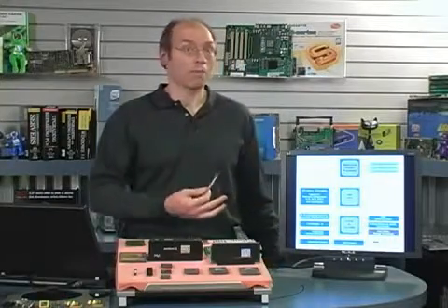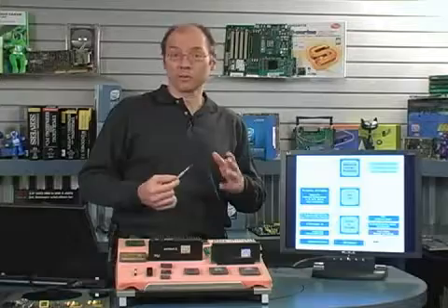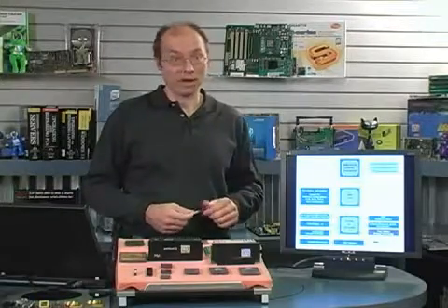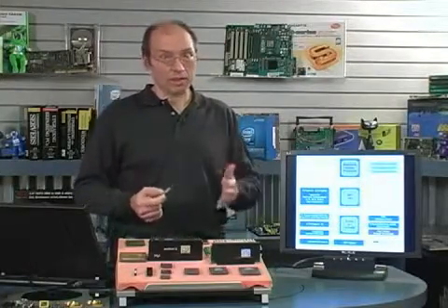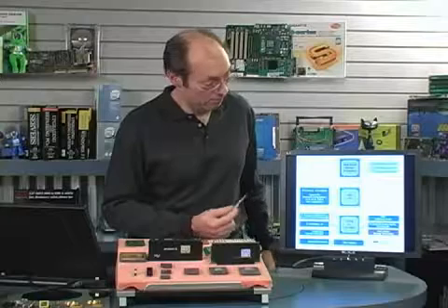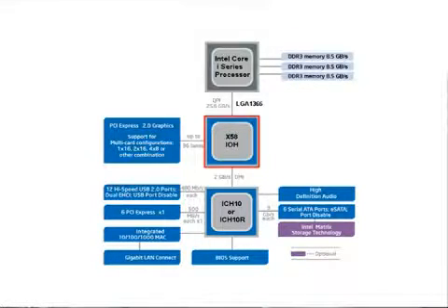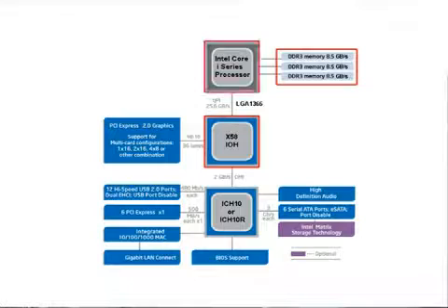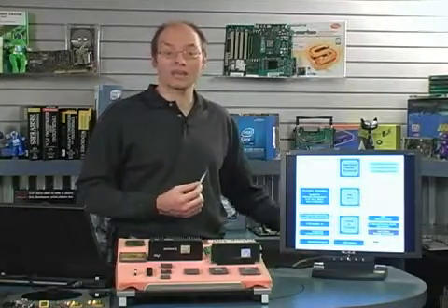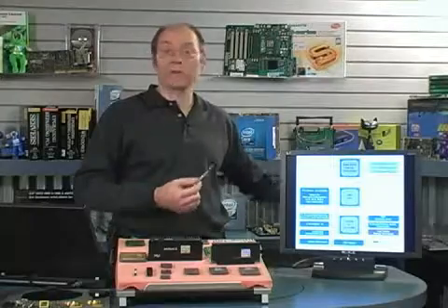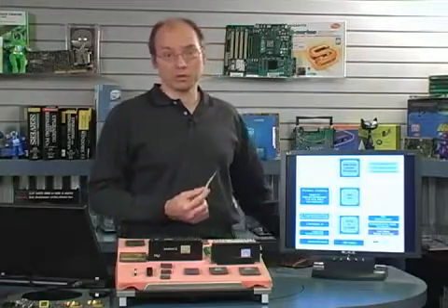Well, AMD in 2003 with the Athlon 64, in addition to originating 64-bit technology, also originated something that was sort of revolutionary. They moved the memory controller from the north bridge into the processor. So now, instead of connecting the memory modules to the north bridge and then having that data have to travel to the processor, now it's connected to the processor directly. Intel has recently also adopted this architecture in the Core i series processors. So the Core i series now in 2008 also have the memory controller built in.